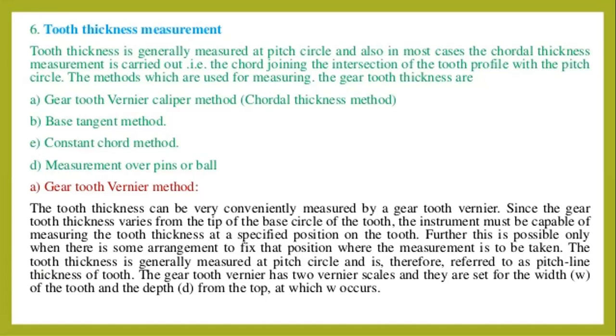So you have to carry the measurement through the chord only. That is, the chord is joining the intersection of the tooth profile with the pitch circle.